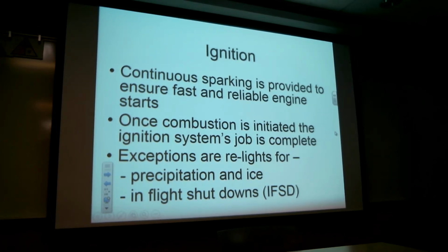So in your glossary, IFSD, make yourself a note, in-flight shutdown. It is like the most blood-curdling sound that a maintenance manager can hear. In-flight shutdown. Now that means the engine has been shut down for some reason, either on its own or due to a maintenance failure that the crew recognizes. And it's going to require an engine restart.